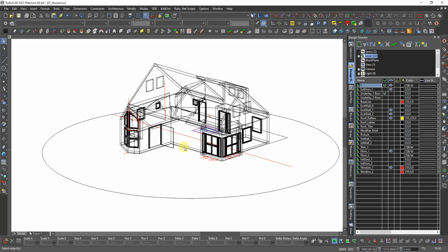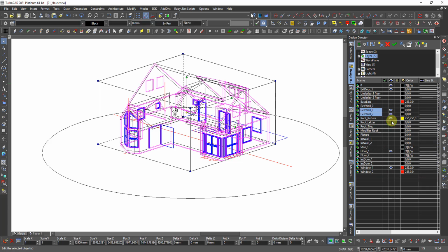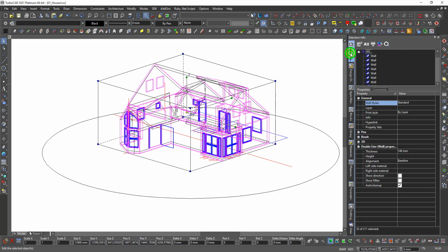Then we can say, I can now use select by. And then it'll be funny to see if something changed. I go and say storey wall 1 and 2, and then I right click and say select by, and I go and change. I collapse this, I say all, and it should not be standard, but it should be deluxe plus 54.